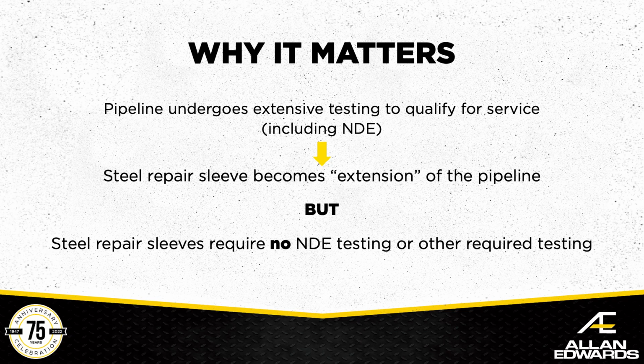And you think about that steel sleeve that you're then putting around it, it essentially becomes an extension of that pipeline. So I think you could then make the argument, well, why aren't we doing that for the steel sleeves themselves? Right? There's no NDE required. Sure, granted, there's NDE after you make the weld on your hot ends or your long seams. You come back and do mag particle. Some may do other methods, but mag particle pretty common there.